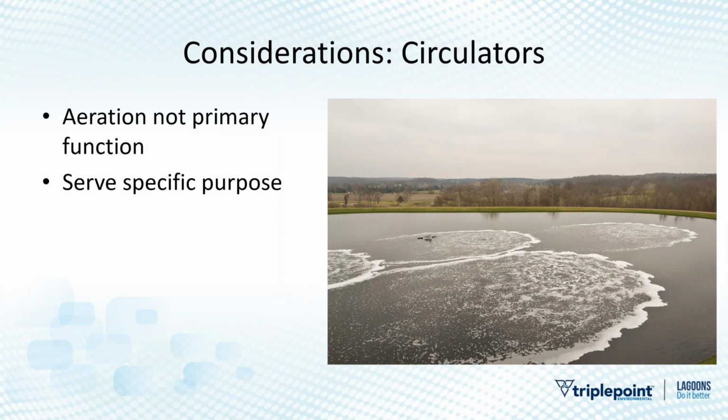And they will argue that, and there's a bunch of companies that do this, that it does increase aeration, and it absolutely does by moving more water across the surface. It's kind of using that facultative methodology of surface area to transfer oxygen. So you are getting some oxygen, but it's not a very high rate of oxygen transfer because it's facultative. It's essentially the lowest rate of oxygen transfer on that list. So people spent lots of money putting these out there to mix their ponds, and they can mix pretty well, but they might not be getting the aeration performance that they need.